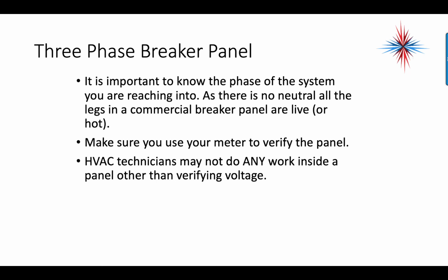HVAC technicians may not do any work inside a panel other than verifying voltage. Again, let me repeat that. HVAC technicians may not do any work inside a breaker panel other than verifying voltage. Your licenses do not allow you to do any work, and this is in almost any state in the country. You cannot do work inside a panel. Be careful.